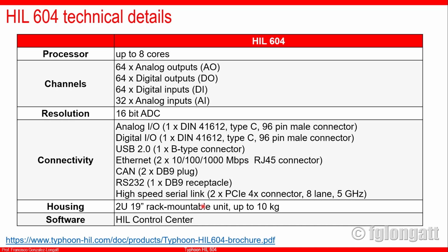And in the case of the analog inputs and outputs, they are able to receive plus and minus 10 volts, symmetrical plus 10 and minus 10. That is a very important feature, especially if you are working with AC signals in a dynamic process of a power system, okay?